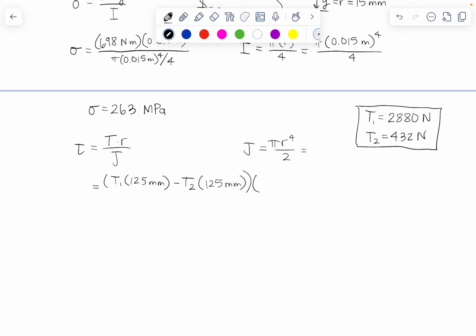So remember that when we're talking about torsional stresses that develop in a beam, they're going to be 0 at the center and maximum at the outside. Imagine twisting a flexible bar. You're not going to be doing anything to the fibers in the center, and then as you get further and further out from the center, you're going to be stretching those fibers more and more.